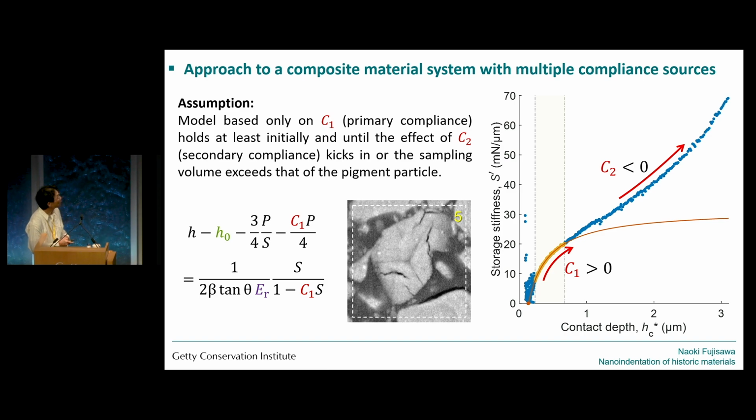This results from compliance, presumably, of this crack here, because this is where we indented, and the crack is so close to the indentation site. But as you keep pushing deeper, you begin to feel the effect of the surrounding binding medium, which is in the black color. And this second compliance source gives you a negative sign because of the relative difference between the two systems.